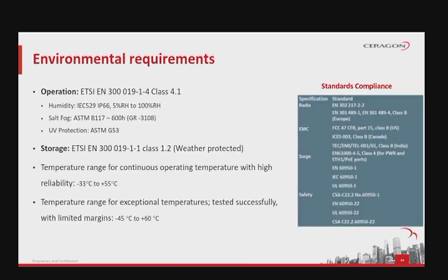Regarding environmental requirements, ip-20c is compliant with international standards in all its aspects, like temperature, humidity and others. As an example, operationally speaking, ip-20c is compliant with ETSI EN 300 019-1-4 class 4.1, while for storage is compliant with ETSI EN 300 019-1-1 class 1.2. Shown here you can observe the temperature ranges tested for continuous operation and also for exceptional functionality